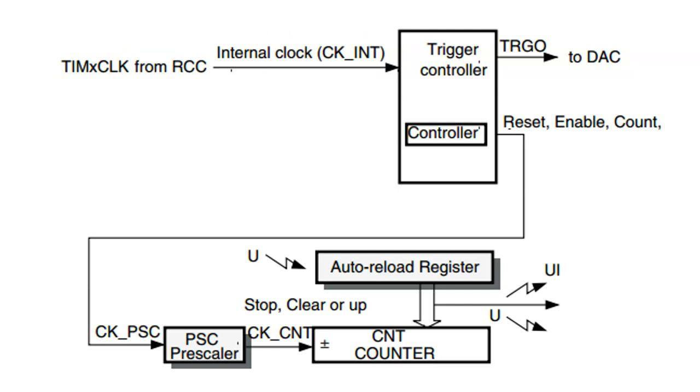There are other modes that are available within the counter that we have. Besides the basic counters, we have a general purpose counter and an advanced counter. Today we'll look at one of the features of these two styles of counters that are related to driving an output pin. It's called output compare. And then next we'll talk about output compare together with generating a specific type of pulse called a pulse width modulation, okay, PWM. First, let's look at output compare.